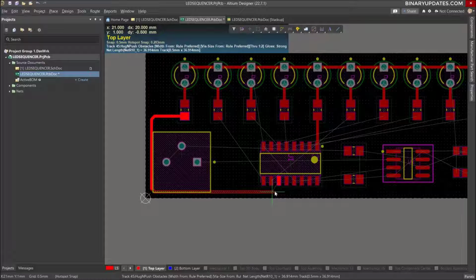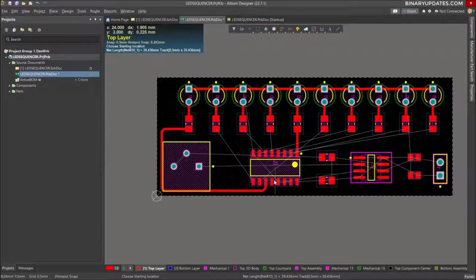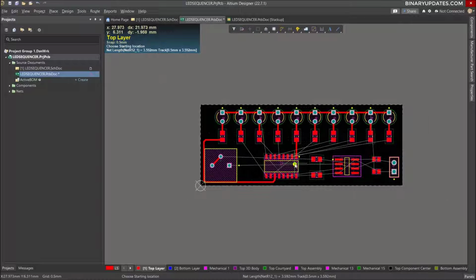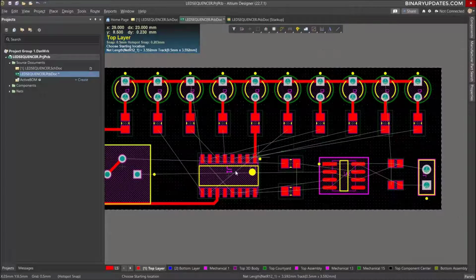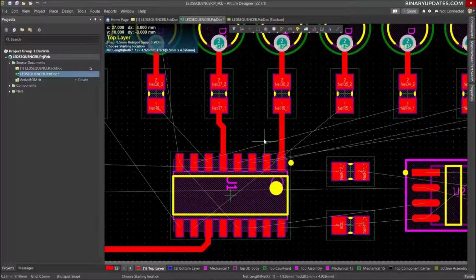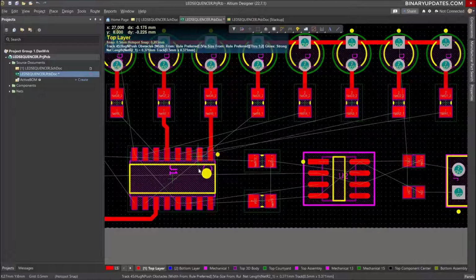This usually takes some time for you to get comfortable, but as you do more and more practice, you will get comfortable. That's how you connect the tracks. Now you can also do the connections of this one, and some routings are easy, some are difficult. So the easiest one I prefer to do first, because it gives a better visibility when we get into solving the complex problem while routing the difficult tracks on the PCB. Then we have this one, and I would rather optimize this leg.